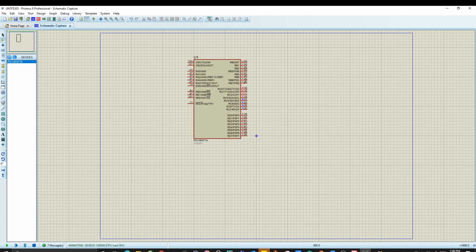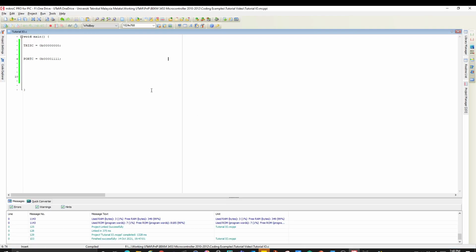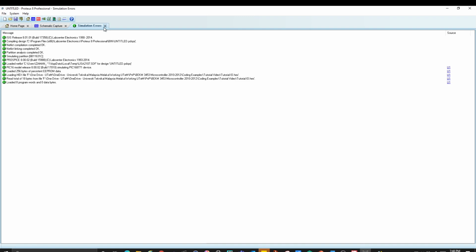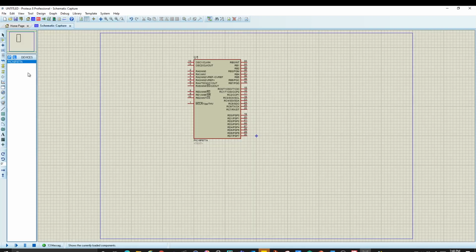So you can see the output from here. The first 4 is 1111 according to this one, right? All this one is high state 5 volt and the other one is 0000 volts. So the blue color means 0 volt and the higher one, the red color, is actually 5 volt. So we can try to measure it. I just want to confirm whether we can measure or not.